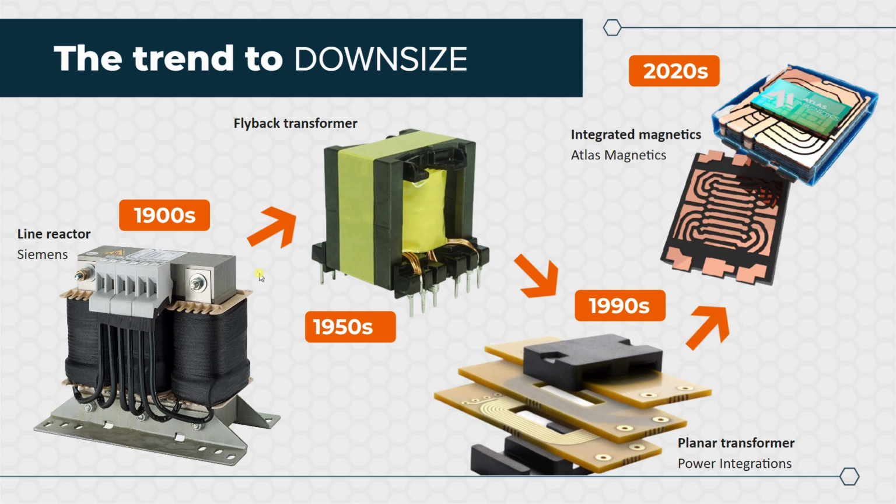As you know, there are capacitances involved, and it is more challenging to etch and manufacture them, so that takes some automatization. People resolved those complexities, introduced planar magnetics, and we are nowadays using them a lot.